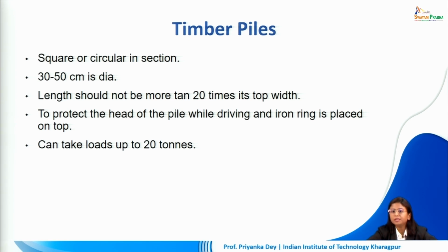It should easily be put into the ground, and it will also have an iron ring at the top where we are going to be hammering it to protect the timber from splitting. This will not be able to take as much load as we were seeing in the concrete pile. It is slightly less. We can take about 20 tons of load.